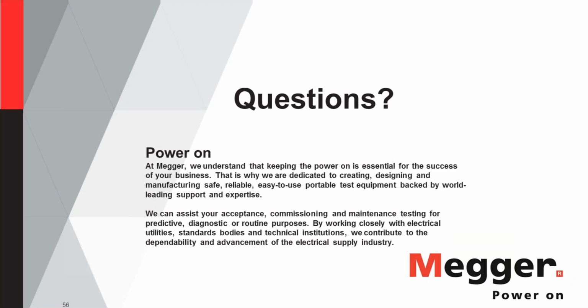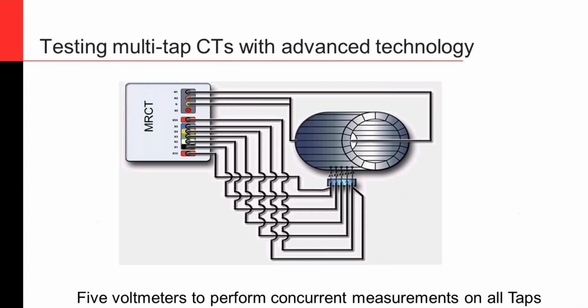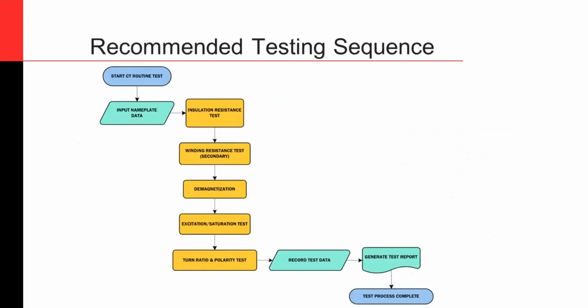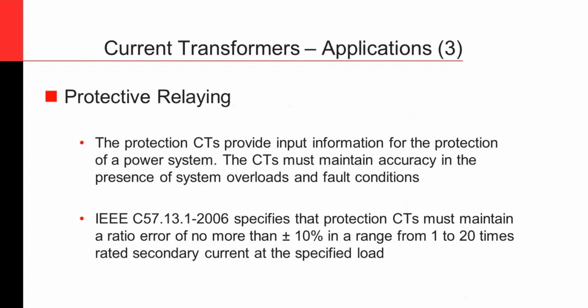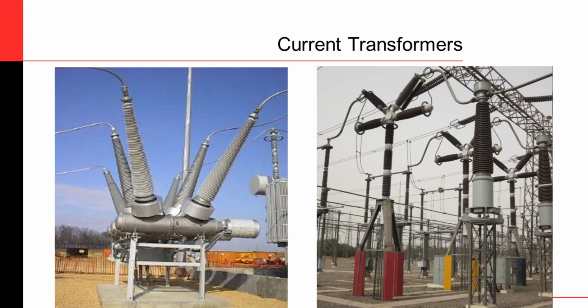Now the next question is, are separate CTs usually used for metering and relay circuits? In other words, relays and metering are not mixed in the same CT circuit. Those are separate CTs, but they can be on the same CT circuit. For example, in one of the bushings, I have to go back to the presentation.